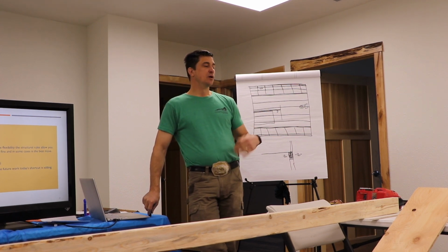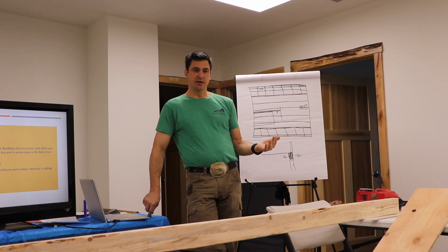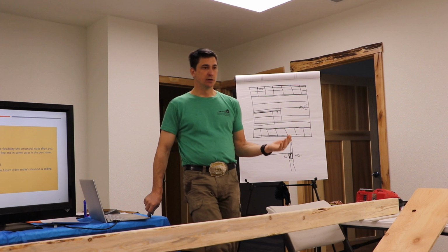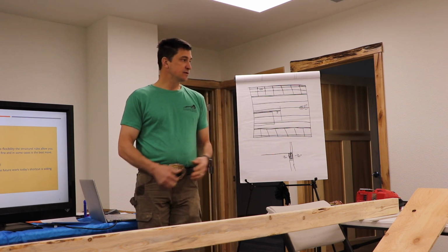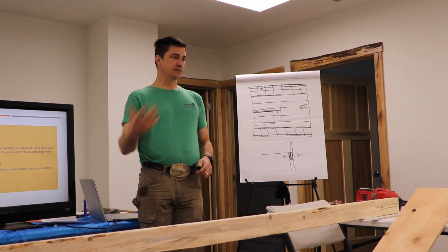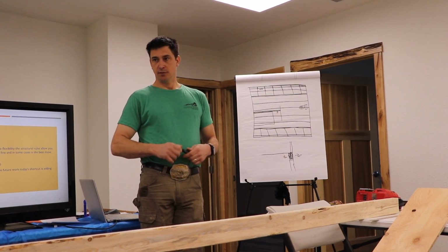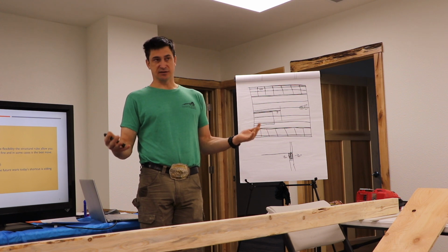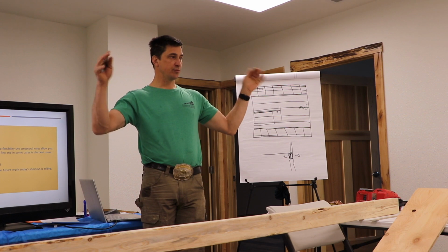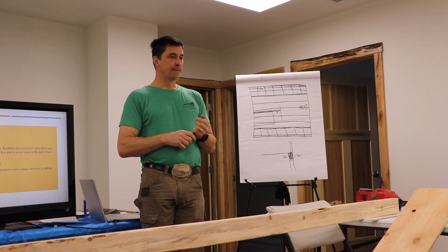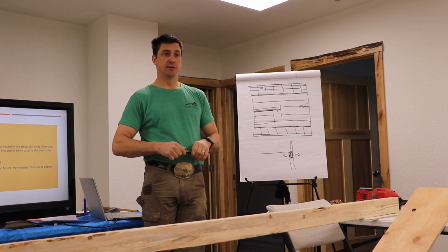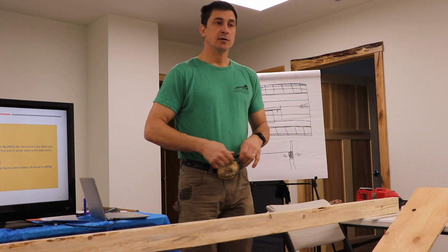Okay? So a lot of guys will come on our job site and they'll be like, why don't you guys have backing in everywhere for drywall? Well, I hate backing because it adds a massive amount of labor, a massive amount of material, and gives a worse product. It takes significantly less time to put clips on your drywall than to put backing wood in everywhere. The drywall for a corner, right? Like in a corner.